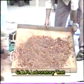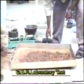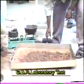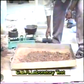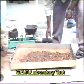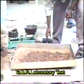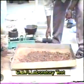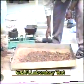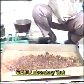Procedure: take 45 kg of material which is dried and sieved through the 20 mm sieve, whose MDD and OMC values are known. Take a sample from that soil of 5.5 kg if it is a gravelly soil, 5 kg if it is a fine grained soil. Mix it with the water up to OMC.